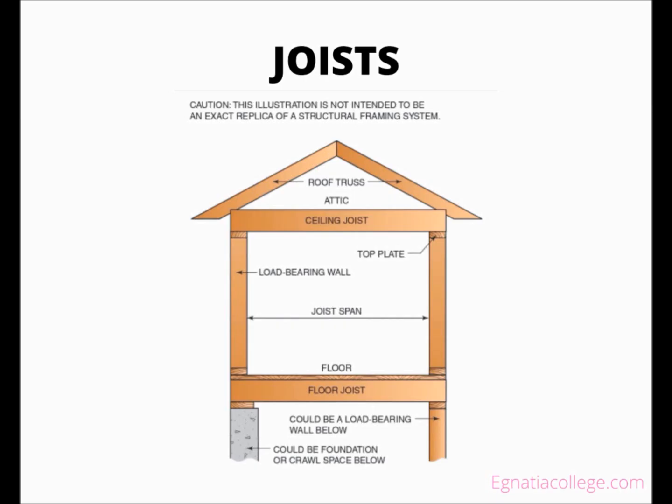The size of a joist depends on the design intent and the structural load of a particular area. Two common sizes are 2x8 and 2x10. But a 2x12 size is used for larger buildings or for greater span requirements. Because a joist has a different structural purpose from a wall stud, it also has different drilling and notching code